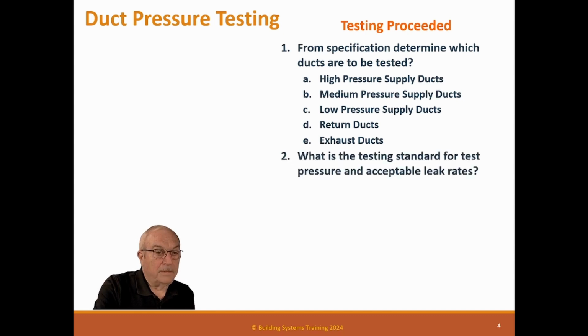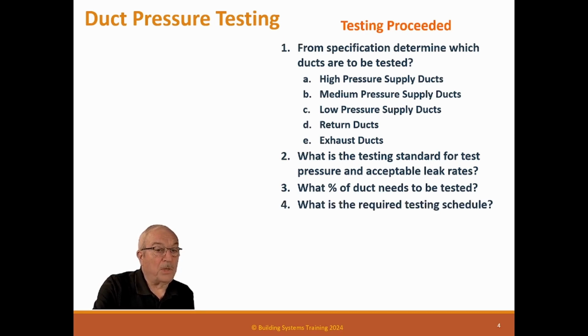We really should. What is the testing standard for test pressure and acceptable leak rates? What percent of duct needs to be tested? These need to be in the specification. What is the required testing schedule? When are these going to need to be scheduled?